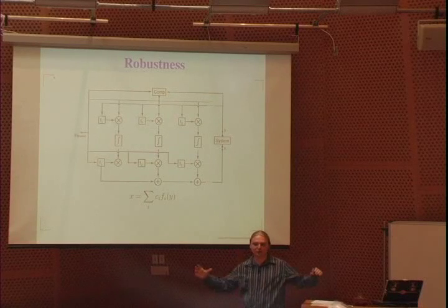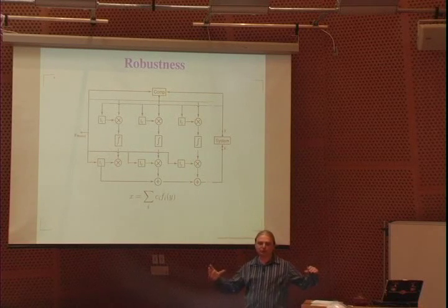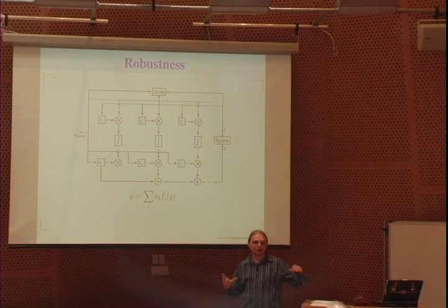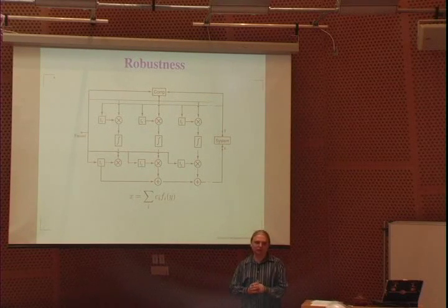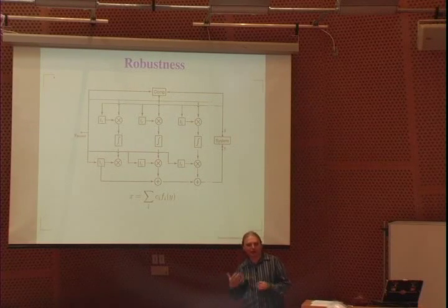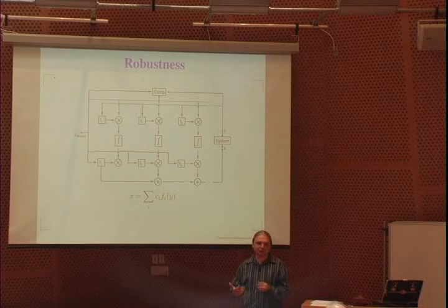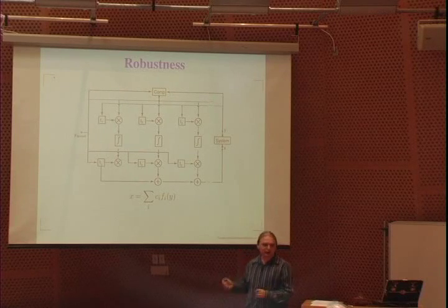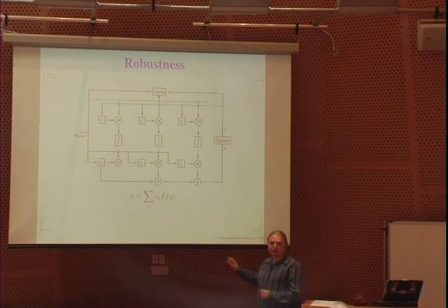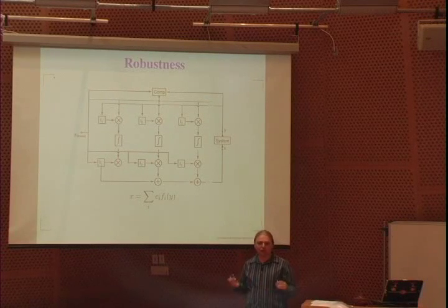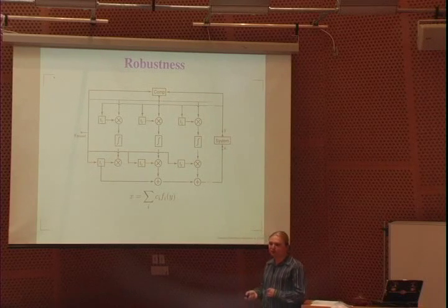People tend to build, for instance, if you're trying to improve the matching between two differential pairs, you just build very large devices, essentially put a bunch of things in parallel, as opposed to putting a bunch of different things in parallel and using that to get better performance as well. And if analog was actually following Moore's law, we would be very close to that limitation. Well, we might get close to that limitation in analog eventually as well. So robustness is kind of a nice property.